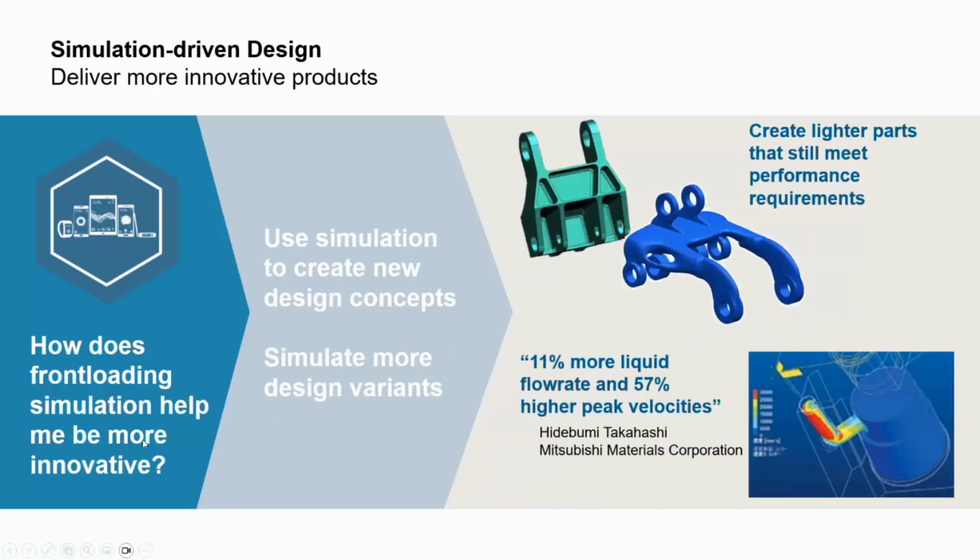How does front-loading simulation help me be more innovative? Mitsubishi Materials Corporation used simulation-driven design to study various variants to optimize the liquid cooling channel opening. That's like the geometry of the cooling channel opening to improve their cooling system performance for advanced cutting tools. So they actually didn't have any specialist CFD analysts, but their designers were able to perform the basic analysis easily inside their CAD environment, and they were able to achieve an 11% increase in flow rate through the cooling system.